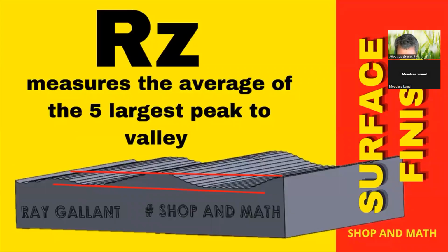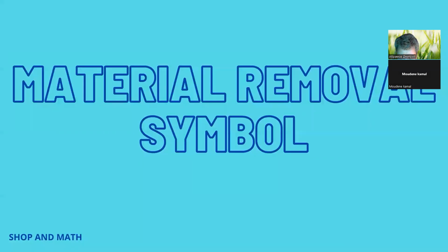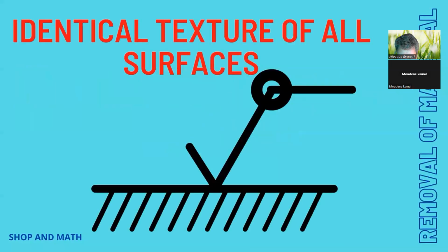RZ is the measurement of the 5 largest peaks compared to the 5 lowest valleys over your sample length. Material removal symbols. Identical surface texture all over. This is one of the newest surface texture symbols, and you probably don't have it in your textbook. But that little circle around the bent elbow means all over.